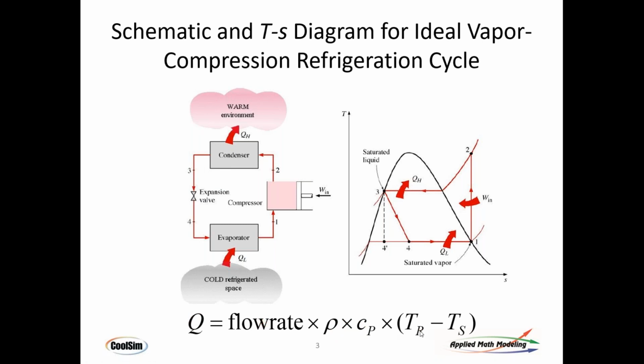Now, I've got here R and S, supply and return. I pulled this out of one of my training slides. That's talking about inside the data center, but it's also the same exact equation out here in the atmosphere. It is the supply and return, sometimes called the suction side and the dissipation side, but it's essentially the delta T across this heat exchanger.